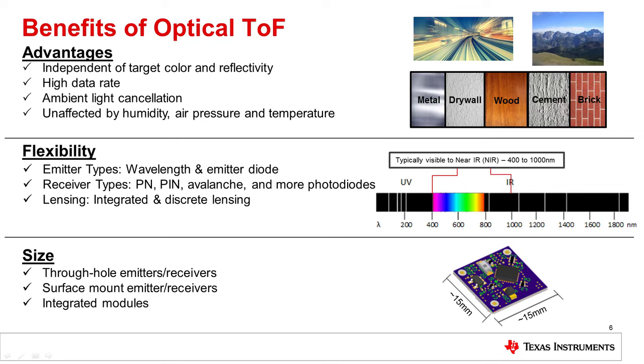When using optical time-of-flight, you are afforded several benefits. Since both types of time-of-flight signal chains, direct and indirect, extract the time travel, the measurements are independent of the signal amplitude. This, in turn, makes the distance measurements independent of target color and reflectivity. Also, being that optical time-of-flight uses light waves as a reference medium, the system speed is predicated on the speed of light. This, compared to other distance sensing technologies, is very fast and allows for reliable detection of fast-moving targets.